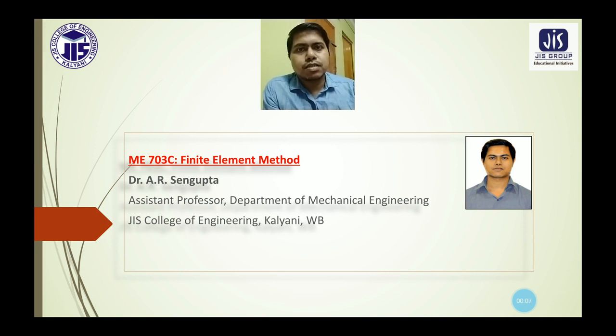So this is the second lecture of the third module, that is two-dimensional problems, and there we will discuss mainly the scalar variable problems. So in the earlier lecture we have discussed the concept of these two-dimensional problems, then the finite element modeling based on the discretization and the numbering of nodes. After that, we have discussed the concept of the CST and LST elements, that is constant strain triangular element and linear strain triangular element, and the comparison between these two different elements we have discussed in details.